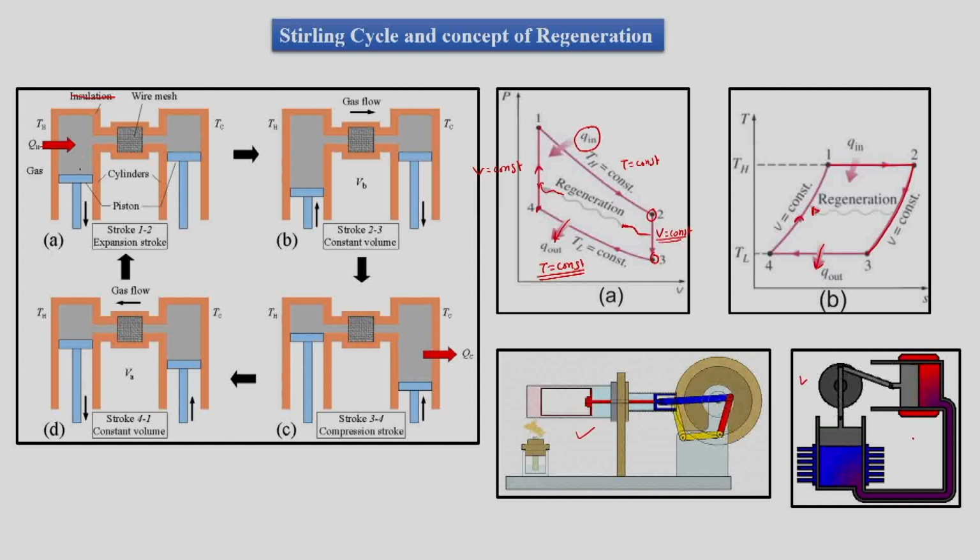So we will have this heat addition process clubbed with the backward motion of the piston, which is in the high temperature zone. So this backward motion is practically expansion, volume is increasing and then heat is getting added. But as volume is increasing, heat is getting added, these two things will get coupled and then we will have constant temperature. So this is constant temperature heat addition. In this case, the second piston is almost stationary, where we will not have much motion of the second piston.